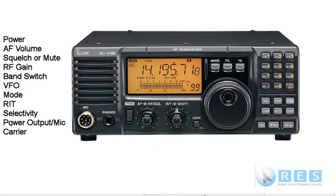Power output or microphone gain. The power output on single sideband is controlled by the microphone gain. So if you had a power meter attached to this radio, a power meter and SWR meter, when you were transmitting, you can adjust your power output by adjusting the microphone gain. The microphone gain is very important because it controls your power output on single sideband.